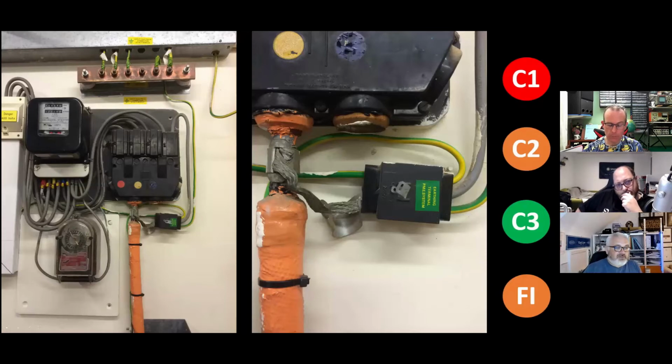Beautifully orange painted PILC cable there with what looks like a variant on a 100 amp fuse. You can see on the left there's a three-phase installation, three-phase meter. John's favourite person staring at us in stereo, which is very strange. That weird phenolic head again. Earth bar, so it's obviously a commercial installation. You've then got an insulated cutout, and a lot of these Henley blocks are now having labels put on them. Earthing terminal, and it says PME system.